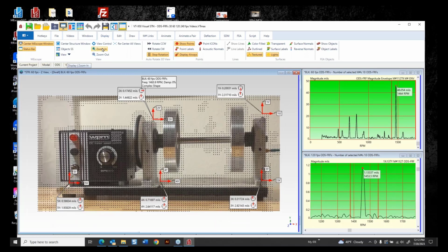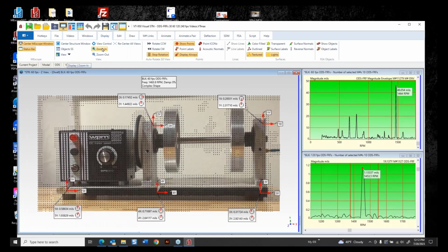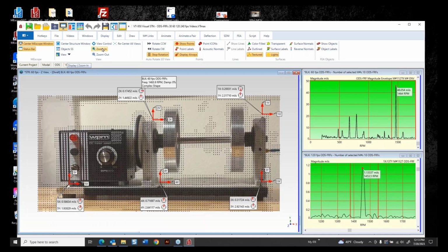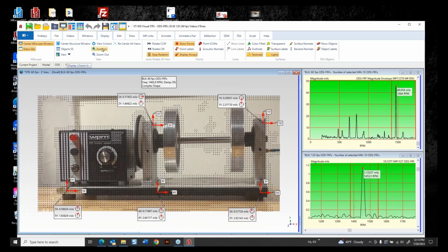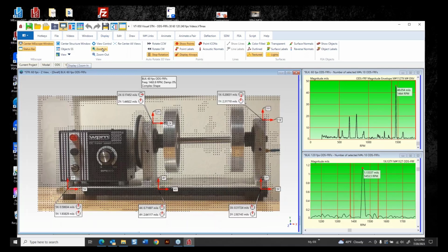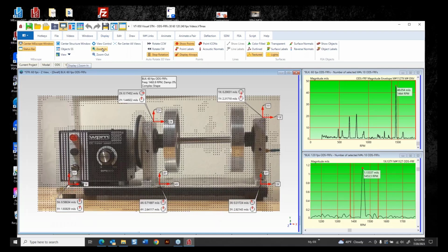And I mentioned that in our software, we can actually unravel the alias frequencies when we know what the machine speed is. And typically that's the highest order peak in the base spectrum. Once we know that, we can unravel. We have what's called an anti-aliasing order cursor.